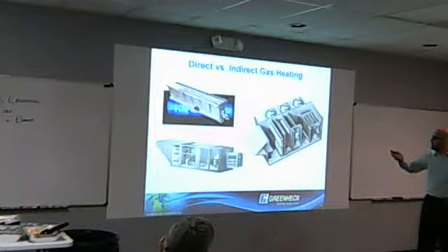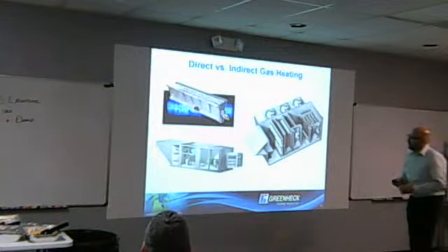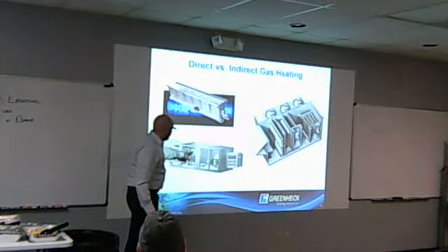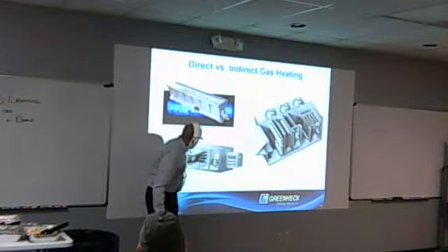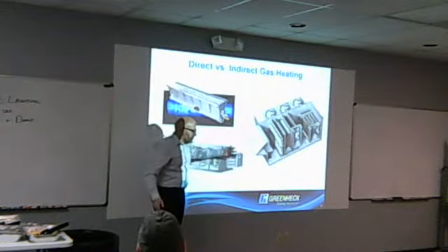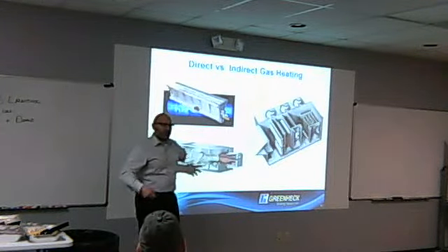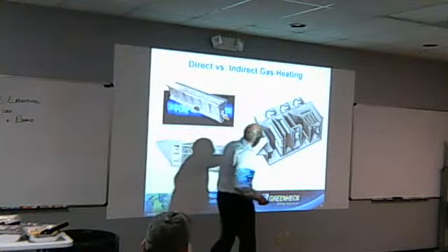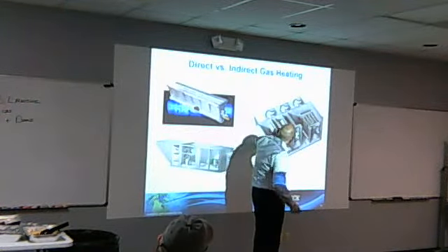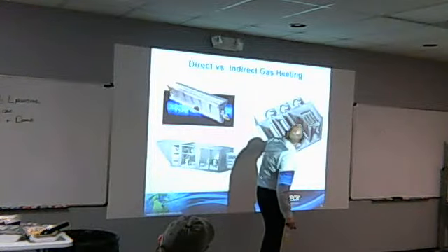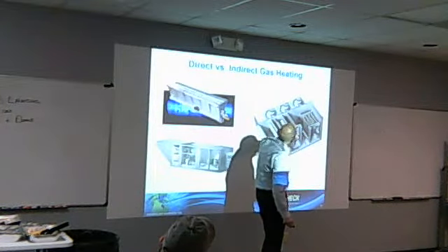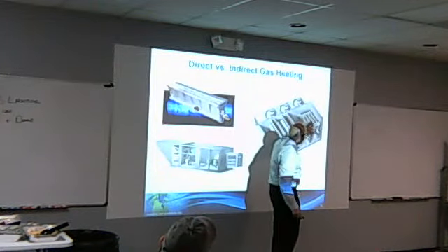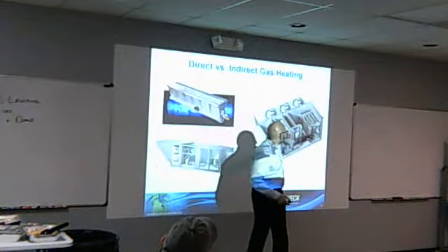Okay, we talked about the burners. This is how it'd be arranged in the unit. This is where I talk about outside air coming in, being filtered across the burner into the airstream. This is an example of a 3-way discharge you might have in a warehouse, just dispersing the air. And then the indirect gas, same thing across the, looks like this one might have additional coils, condenser, probably hot gas reheat, DX coil, and then across the heating section into the space.